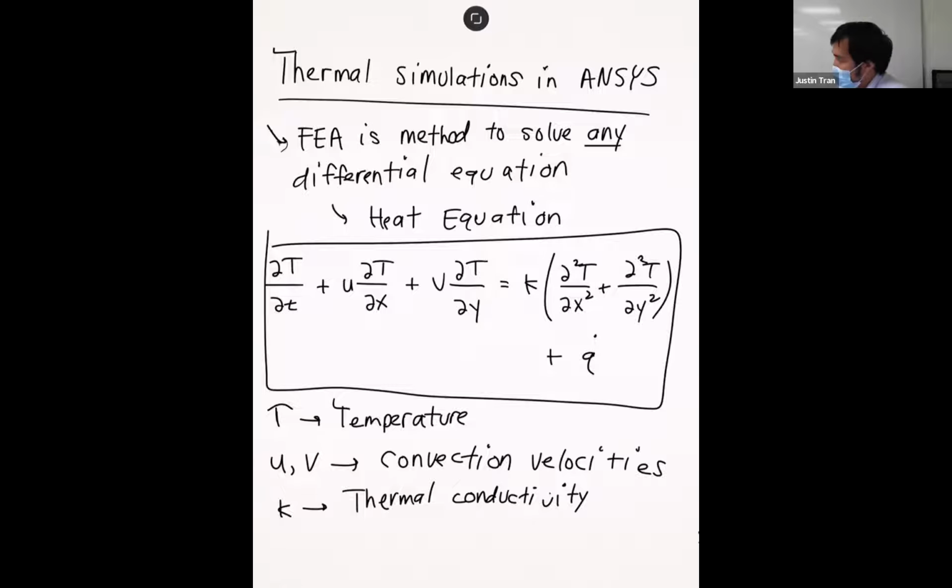It expresses how easily heat can move through a material. Metals are great conductors of heat. If you've ever touched a hot frying pan, you will agree with me. The thermal conductivity for metals is extremely high, but for certain materials like styrofoam, it is very low. That's why you can pour hot coffee into a styrofoam cup and it won't burn your hand.